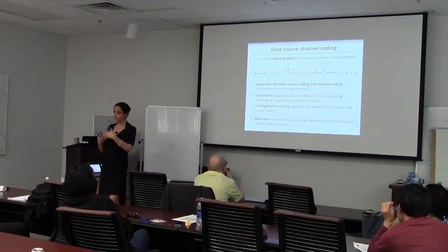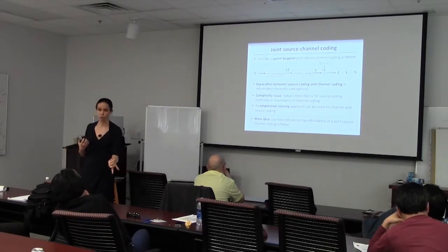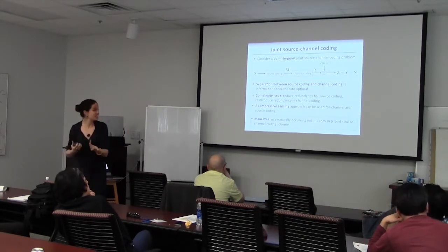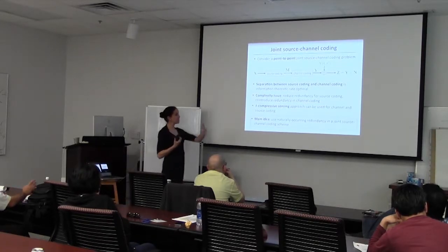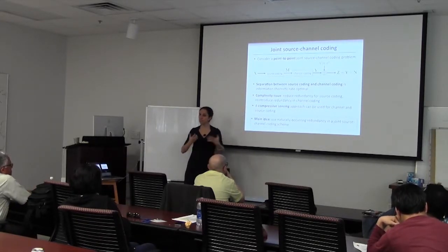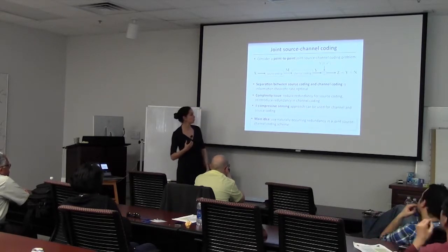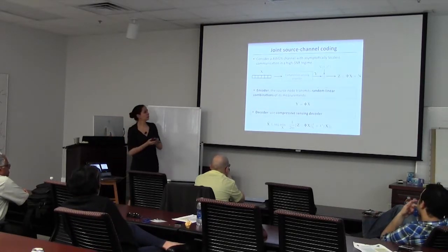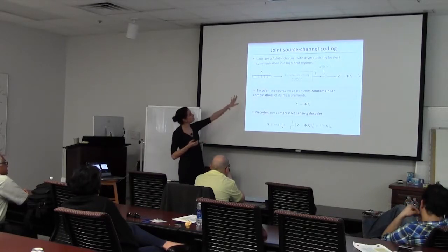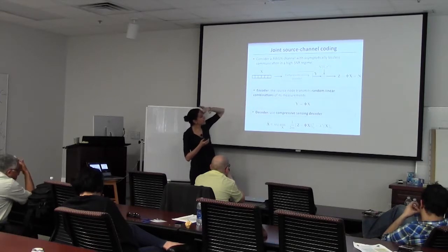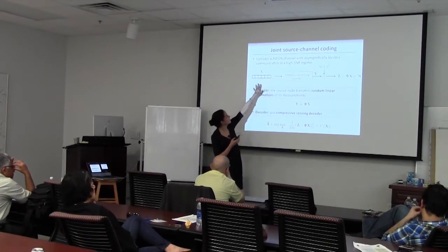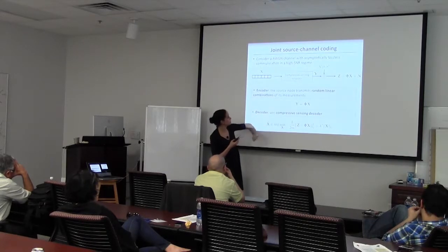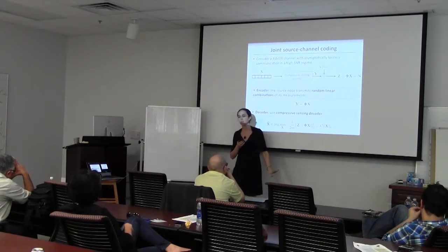So I first squeeze every last ounce of redundancy, and then I add it. Now, of course, the naturally occurring redundancy might not have been the right redundancy in the first place. That's for sure, right? It might not have been the kind of redundancy that helped me with the channel coding. On the other hand, whatever happened to be there that might be helpful, I don't necessarily want to squeeze out, right? So this is allowing me in a way to modulate the two a little bit more subtly, okay? And the very simple approach that you could use here, for instance, is, so I consider an AWGN noise, and I look again at the high SNR regime where, yet again, I'm being extremely sloppy about what I mean by this. I could basically think of having a source node which is transmitting a random linear combination of its measurements, okay, and then just using a compressive sensing decoder.